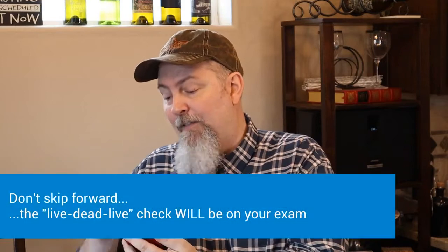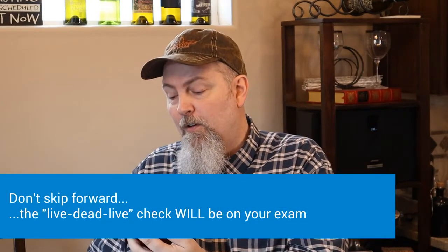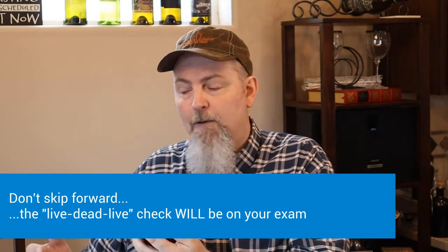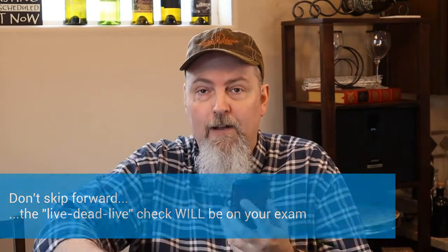If this is 110 volt AC, I'm going to test my voltmeter on a live 110 volt AC circuit. I plug it in. Oh yeah, that circuit is live and my voltmeter shows 110 volt AC. It's working. I unplug it, then I plug it into my computer and it says 0 volts. Okay, now I know it's de-energized, maybe. So we've done the live dead part.